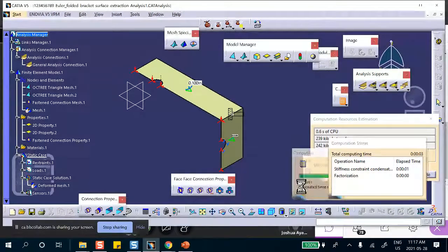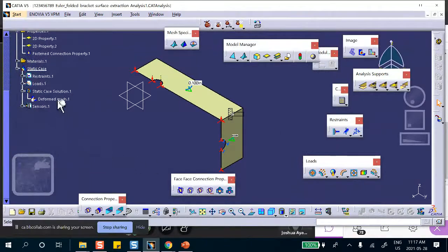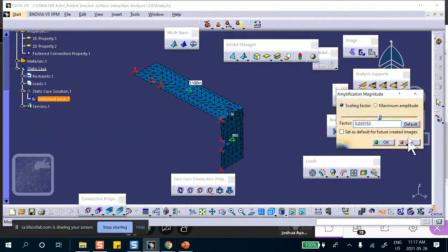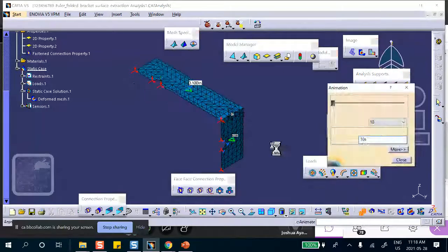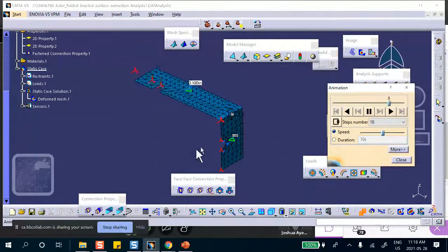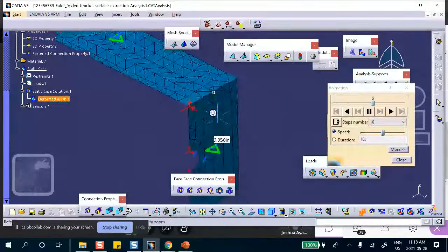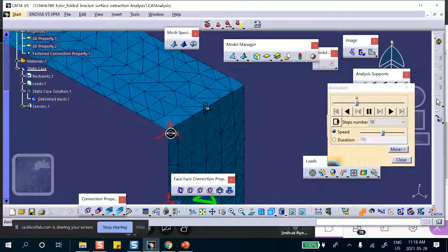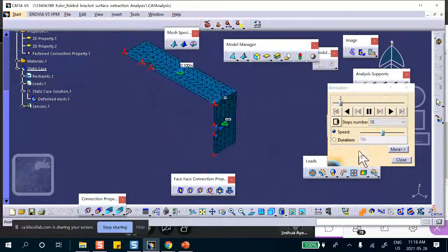I'm going to change the scale so that you can see it better. Remember this scale, when you plot something, you can change the scale. Deformation. Change the scale to default. That's the way it's supposed to be, right? This is supposed to bend. It's making this guy bend too. You can see that. Not only does it bend, but it also makes this bend because these are talking to each other now. And the same thing with displacement and the same thing with stress.